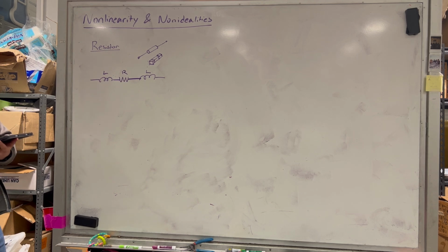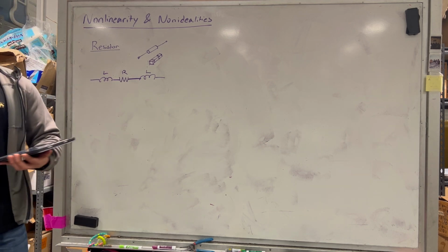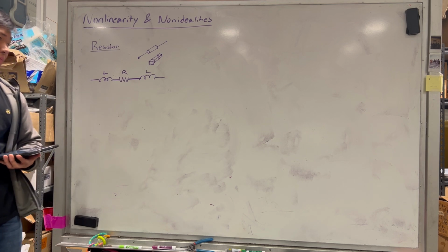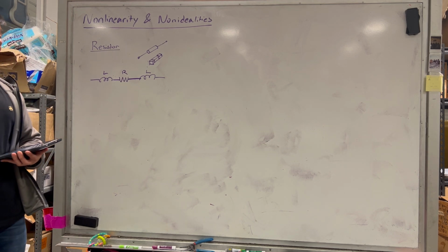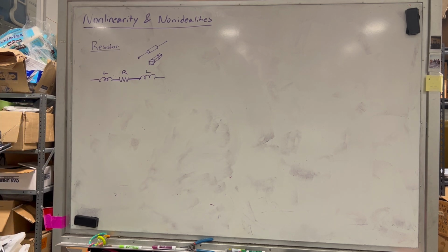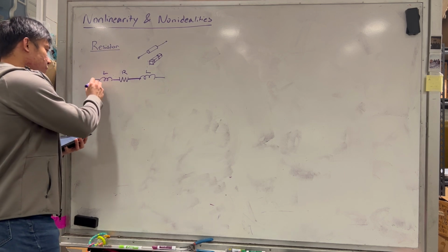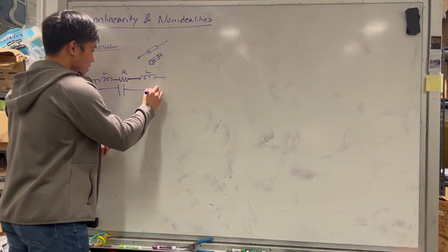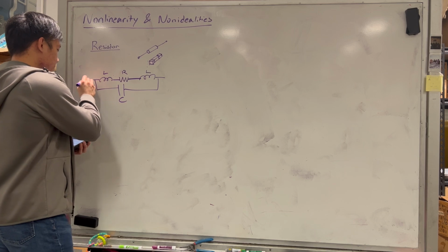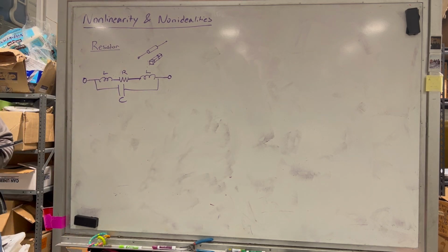And finally, within each resistor there are particulates, and how it's constructed degenerates these resistances by some type of dielectric particulates in the material, and that could be modeled as some type of capacitance. So you have some capacitor that goes in parallel with everything, right? So you get something that looks like this.